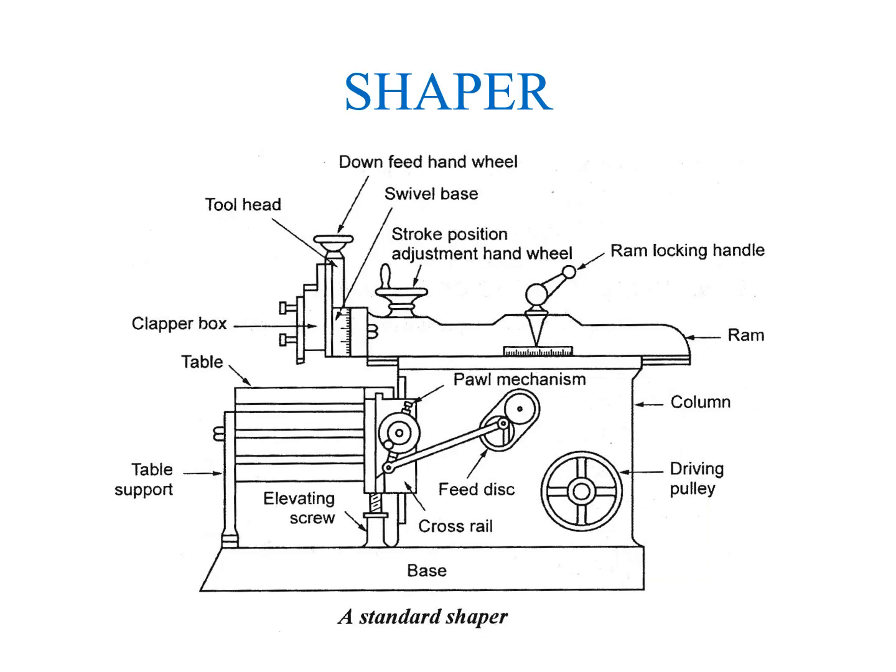Next, shaper machine. First, the shaper is a machine tool used primarily for producing a flat or plane surface which may be horizontal or vertical or an angular plane, and it is used for making slots, grooves and keyways. It is also used for producing contours of concave, convex or a combination of these.